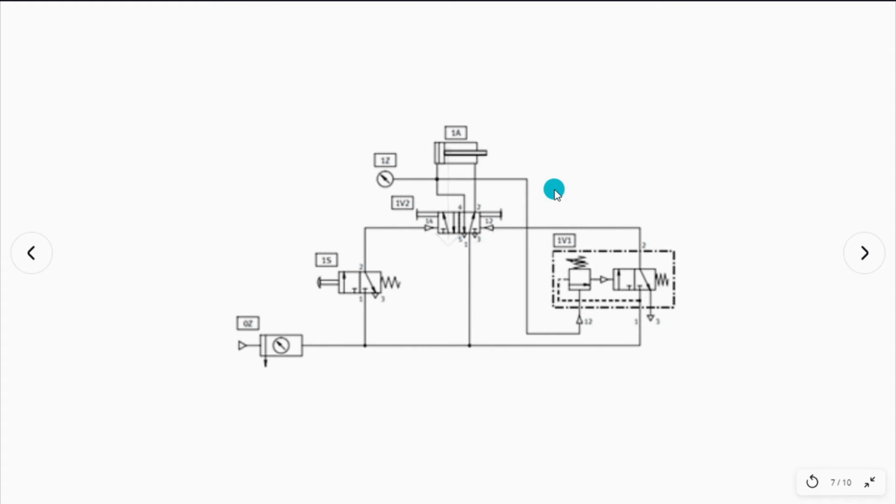So if you can see, you have two inputs for your sequence valve. One will come from your supply element and one will come from a signal to know if pressure has accumulated. So an overall function of this circuit is when you push now your switch 1, it will fully extend, and when it is fully extended, it will actuate your sequence valve and it will eventually retract.